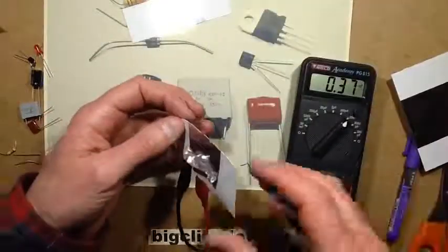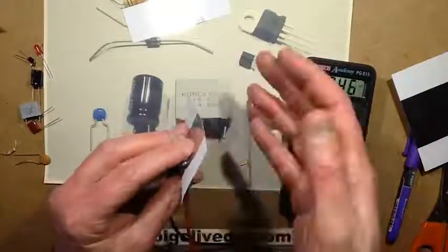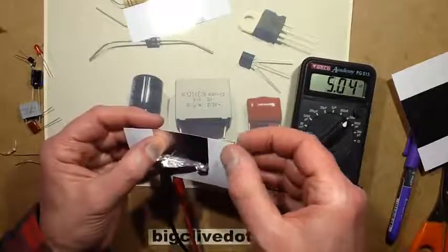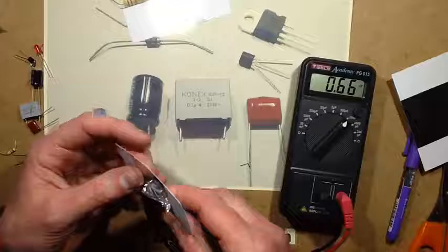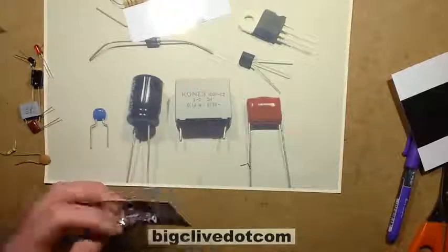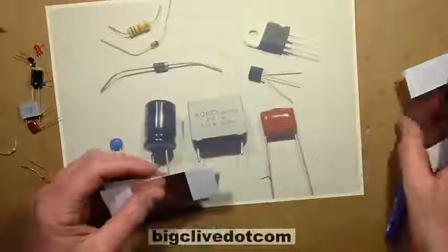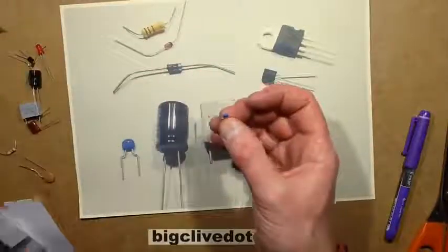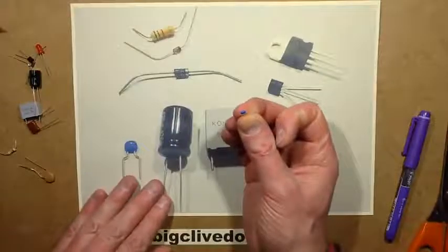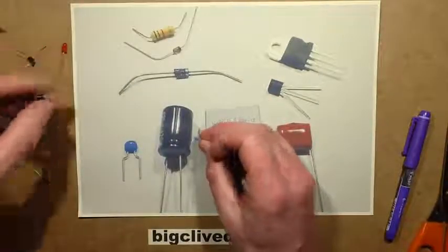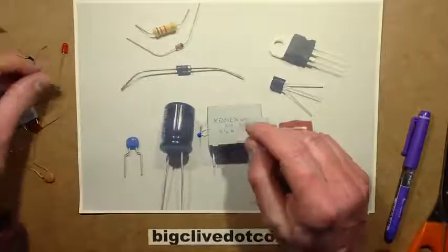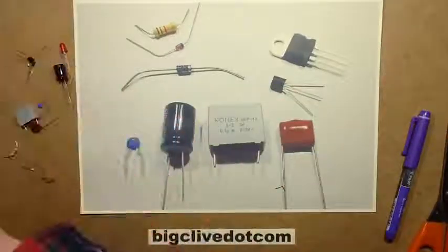So that's basically how a capacitor works. It's an insulator with 2 metal plates on either side, and the area of the metallization and the thinness of the separator is what determines the capacitance. And in reality, for components like this little one, keep in mind that I managed just a couple of nanofarad. This one is rated 100 nanofarad. And if you look at things like this, this is an electrolytic capacitor which is rated 470 microfarad, which is a massive capacitance.